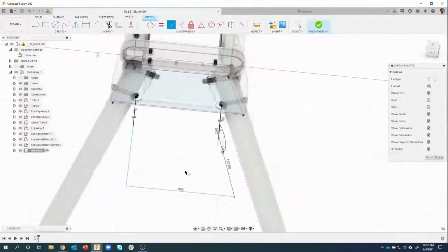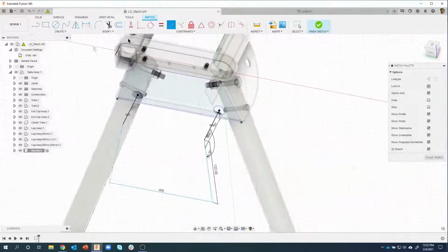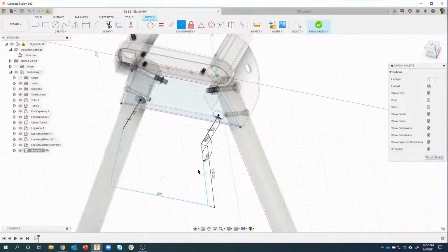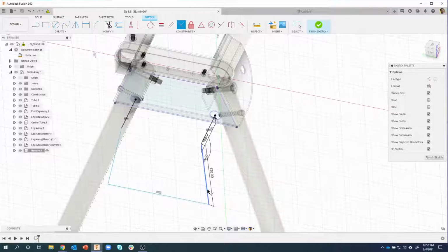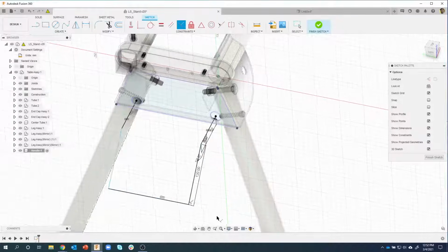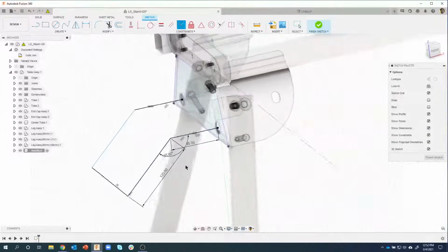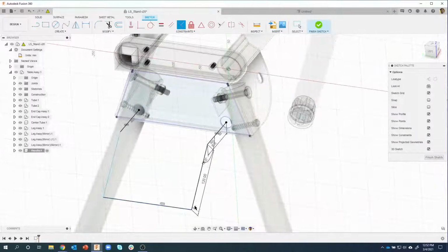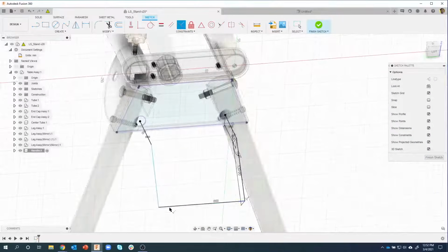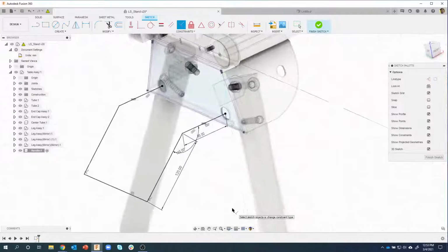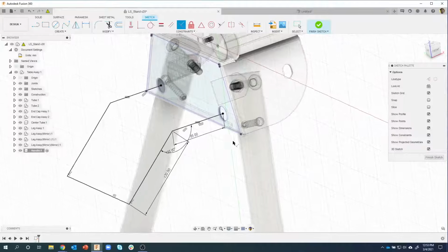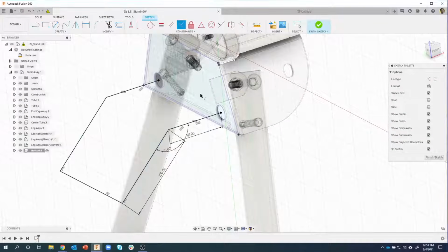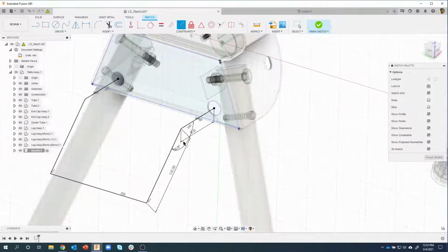Okay, that looks good. Oh, I know why. Duh. I want to do perpendicular, like so. There we go. So you can see how I'm using constraints, and I basically said that has to be 90 degrees. I could do the same thing here, make sure that's perpendicular, and now we can see that sure enough my sketch is fully constrained in 3D.